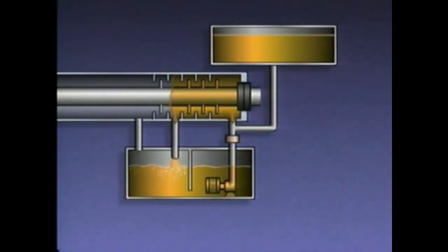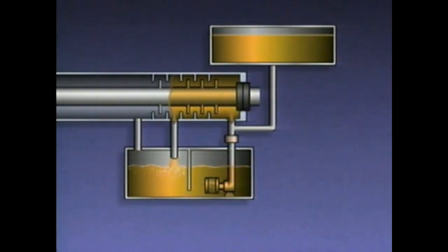As the oil comes in contact with the gas in the compressor, some of the gas is entrained in, or carried along with, the oil. The gas separates from the oil in one of the compartments of the oil reservoir. The gas rises up through the oil and returns to the compressor through a gas return line. The oil flows to the oil pump and is then returned to the seal. The head tank is used to supply oil to the seal if the pump fails.